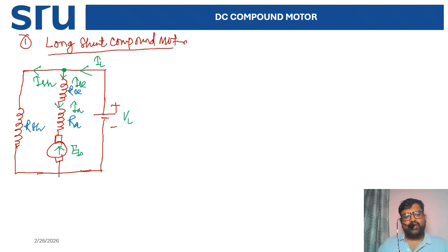When I come to this circuit, I will explain the long shunt compound motor initially. First, for simplicity, put some nodes here, whatever you wish: A and B, C and D, and E and F. If the circuit is connected in parallel, then when the current is divided into two parts, everybody write down the first current equation: load current equals series current plus shunt current, right?